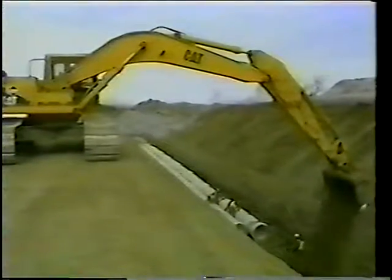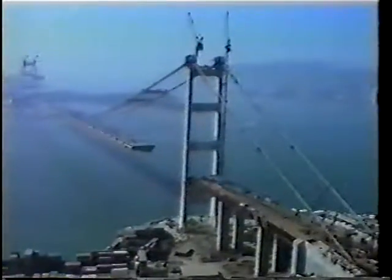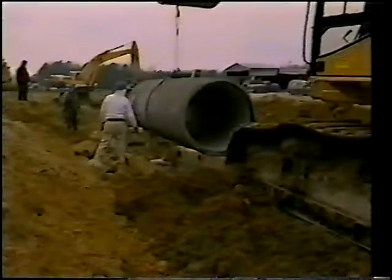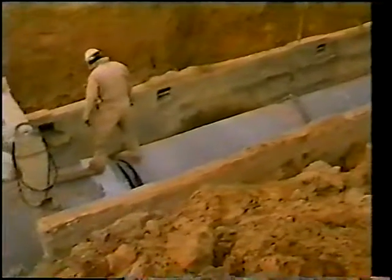Engineering science now allows us to design and construct efficient, durable underground pipelines with the same precision as we can build above-ground structures. But there is one big difference. An above-ground structure is a structure by itself and is designed to carry all the loads imposed. Most buried pipe rely in some way on interaction with the surrounding soil to carry loads. Virtually all buried pipe depend on proper soil support and therefore proper installation to provide good structural performance.